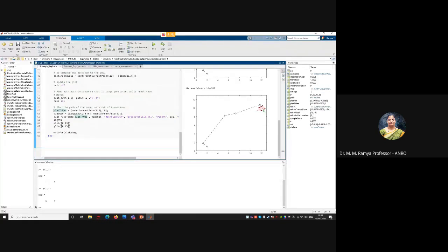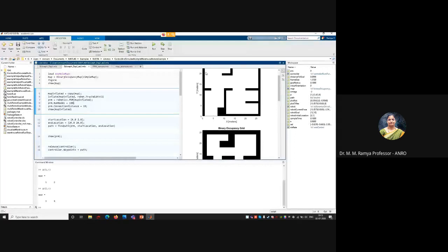When we talk about the robot, we are talking only about the center point of the robot as X, Y. What will happen when the robot's X, Y is taken here? If X, Y can travel till this corner, what will happen to the remaining half of the robot from the center? It will crash on the wall.